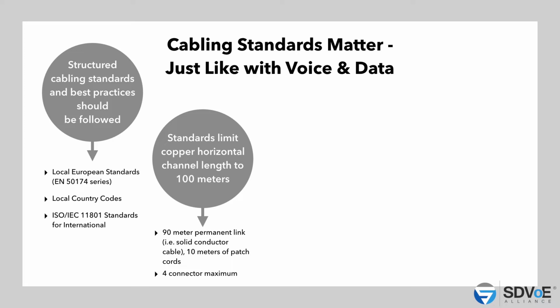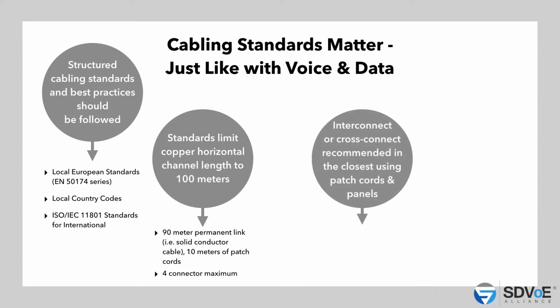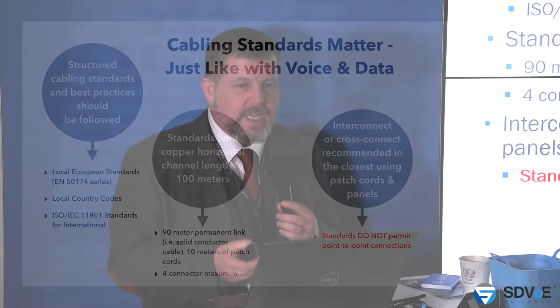Typically no more than 4 connectors in a channel. Now typically standards don't talk about point-to-point connections, and this is actually not in terms of performance, it's actually talking about flexibility within your system. What we're trying to do is create as much flexibility for thinking about moves, adds and changes.